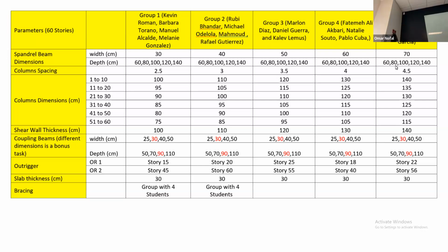Okay, but when I'm saying base model, not only the geometry, we are gonna assign the loads, assign everything, so that we don't need to redo the work. We are just adjusting one parameter. Because if we didn't assign the loads and we make save as and we build, for example, 30 models, you need for each one of these 30 models to assign loads. Okay, so we assign the loads one time and do everything one time, and by just 1 minute of your time, you will go to your model, select something and change it and save it. Okay, so we did this, and that.